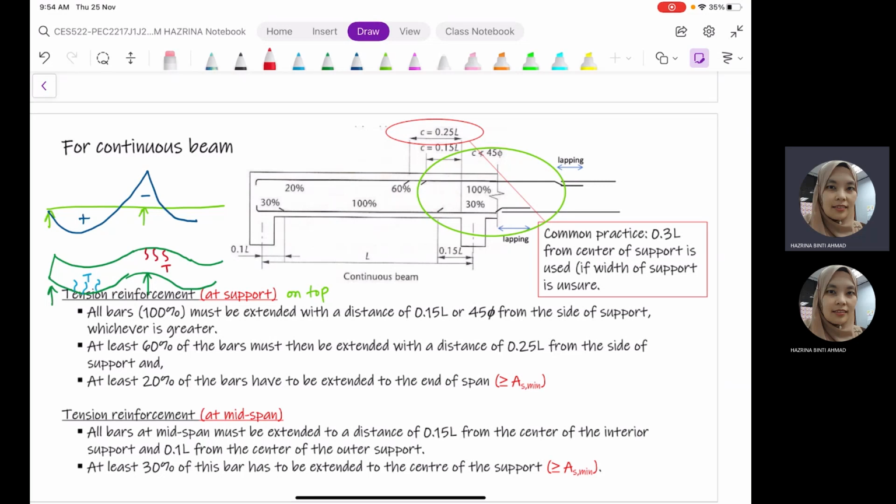As for this, we will be providing the main reinforcement at the place where our beam is subjected to tension. If the bending moment is positive at midspan, the main reinforcement will be placed at the bottom. However, at the support, since the tension zone is happening on top, the main reinforcement will be placed on top. So if we are looking at these curtailment rules, the reinforcement here that we are looking at is the main reinforcement at the support. It is sitting on top.